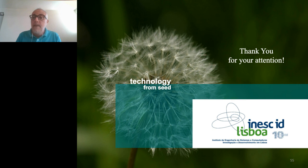And this is quite fair, because when you use HLS with traditional binary systems, the design automation tools for sure do the best for achieving the best arithmetic units that you can have for binary systems in this particular technology. So what you do is patch in these unconventional arithmetic units that you optimized for the technology, and you use them in HLS descriptions.